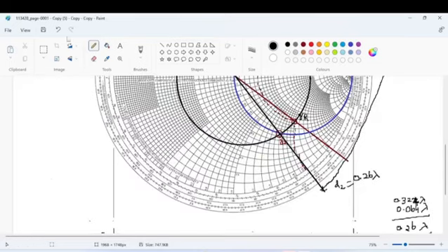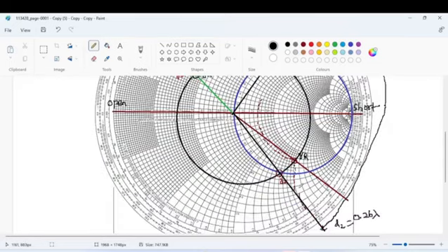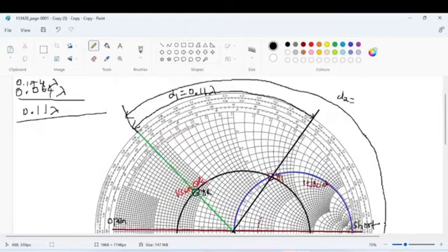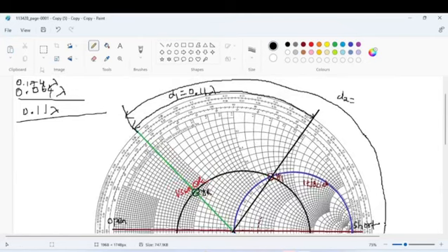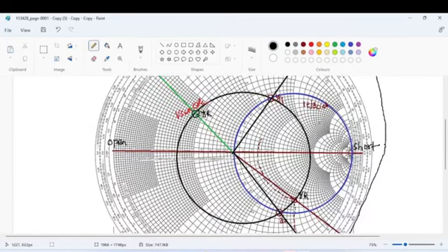Don't go anti-clockwise. People will think, y1 to y2 is very near, sir, so can I mark y1 to y2 in a backward manner? Is it not the correct way? Always you need to move towards the generator. Don't move towards the load. Okay, so that is the procedure. Always you have to move in the clockwise direction, right?